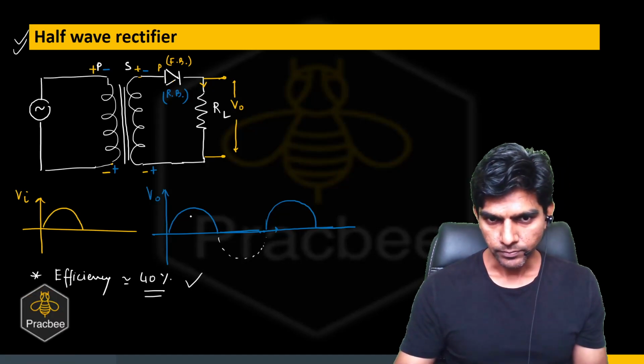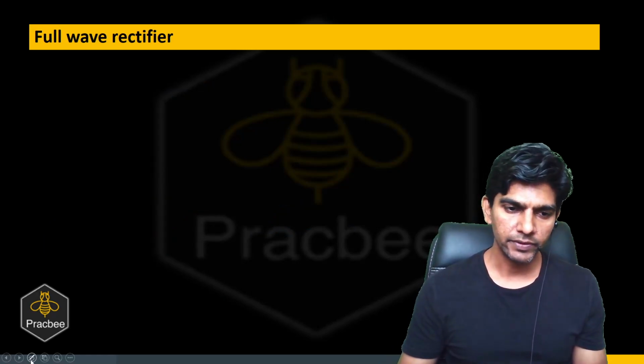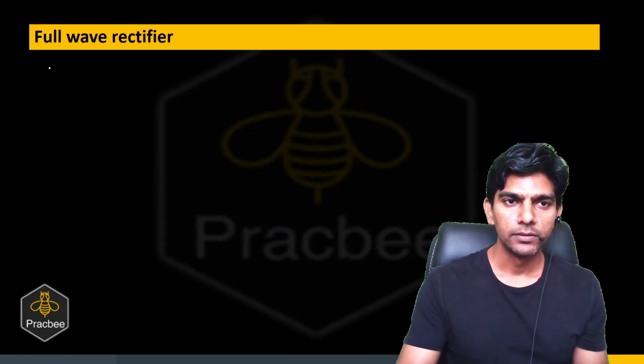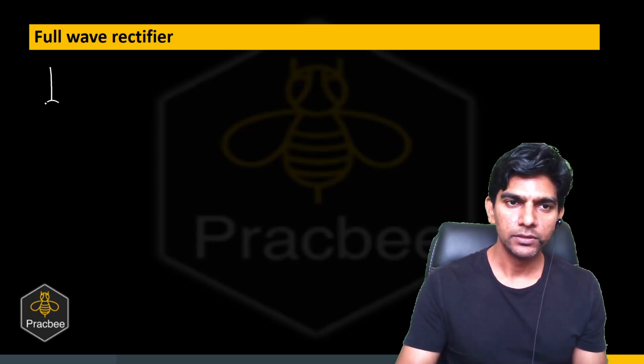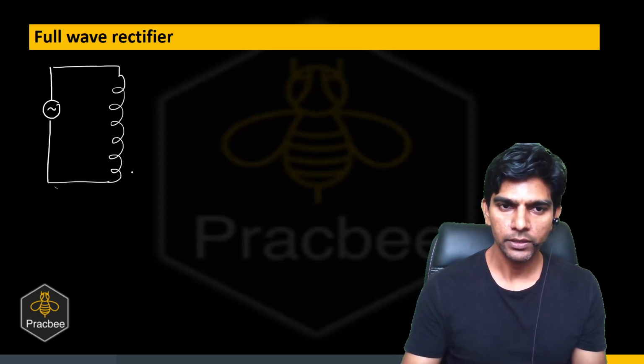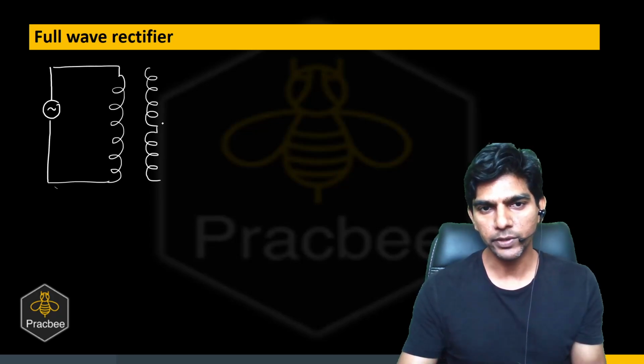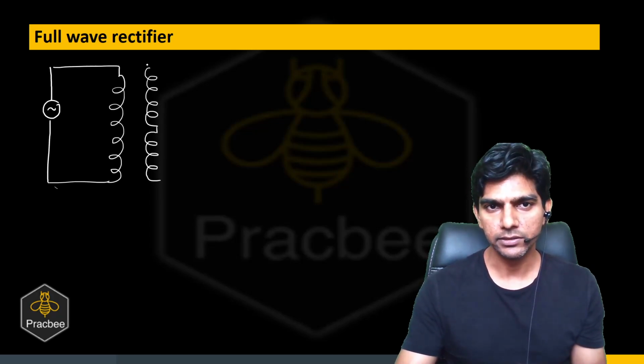Now, let us see a full wave rectifier. Again, we'll feed AC supply to this rectifier, and again we have a transformer, but now we have a special transformer. It is known as a center tap transformer. In a center tap transformer, the secondary winding is made up of two parts. So we have two coils in series,